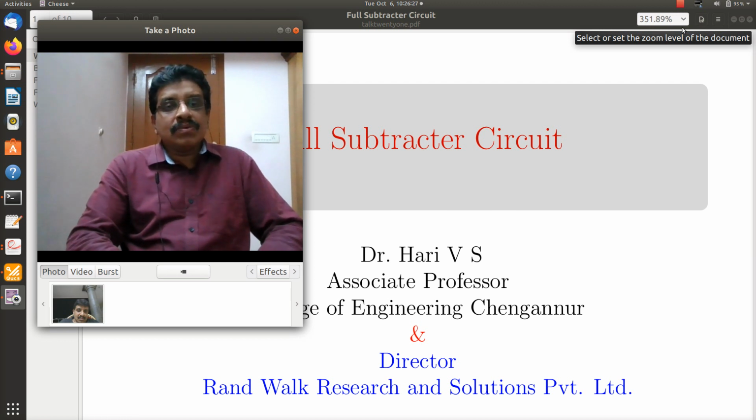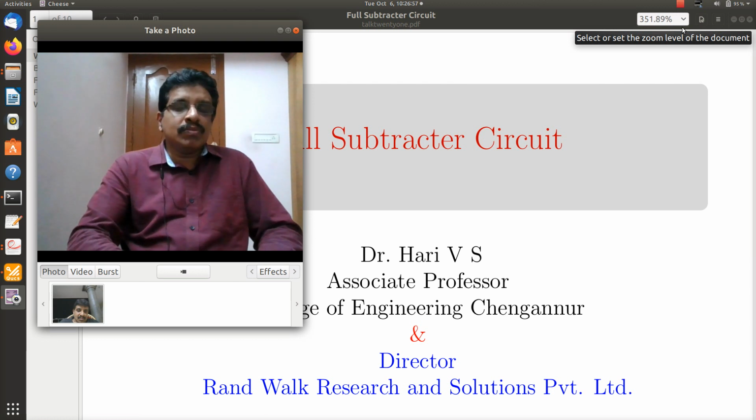It is very similar to a full adder except that instead of the carry input I have a borrow input. So in one full subtractor circuit we subtract two bits xn and yn and borrow from the previous stage bn minus 1. So I make the operation xn minus yn minus bn minus 1 to get a difference bit dn and the borrow in the current stage, or borrow that is to be propagated to the next stage, borrow output. So let me start with that presentation.